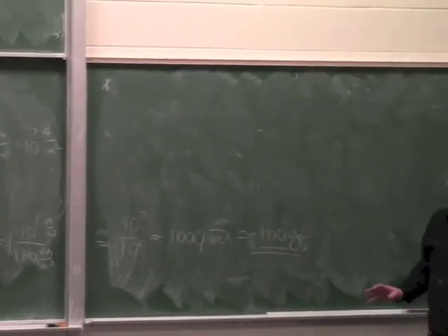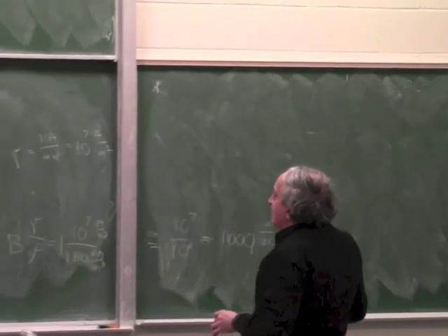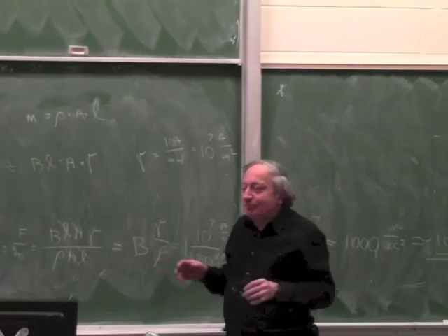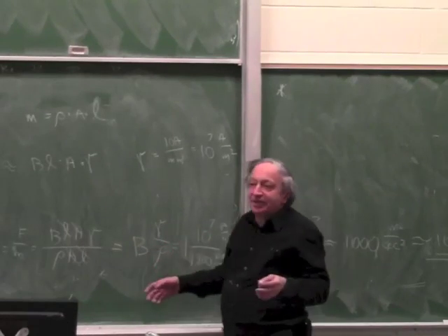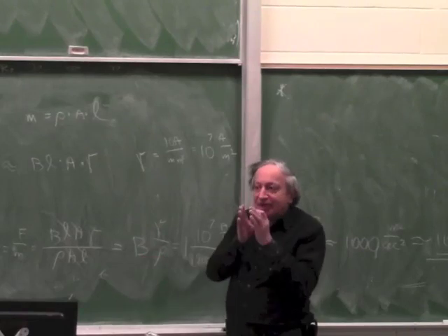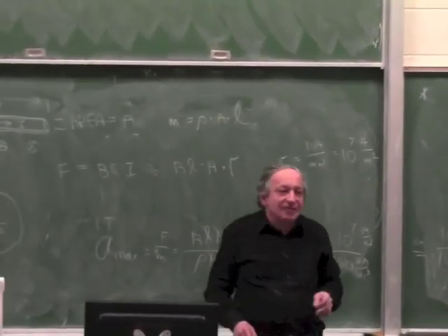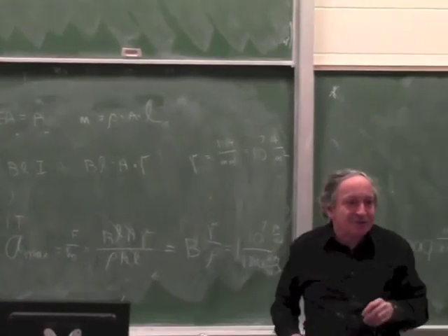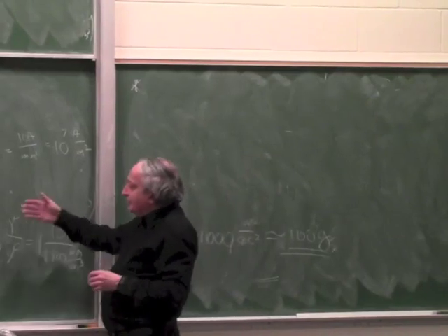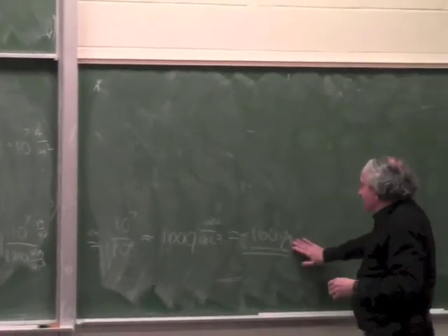So basically the bottom line of the story is that moving coil actuator performance is strictly limited by the properties of materials. There's no big theory behind it. And B is limited by the quality of magnets we can get. If we take the best magnets we can get, like rare earth magnets, because we need an air gap for the coil, we are basically limited to 1 Tesla, unless you do heroic measures, like in MRI machines. Okay, and we take copper, which is a very good conductor with a certain power density, divide by its density, we get this. So what can we do better than that?